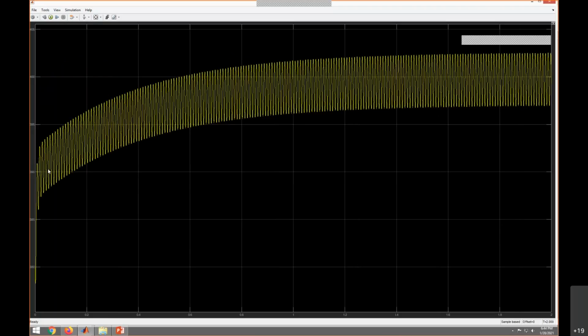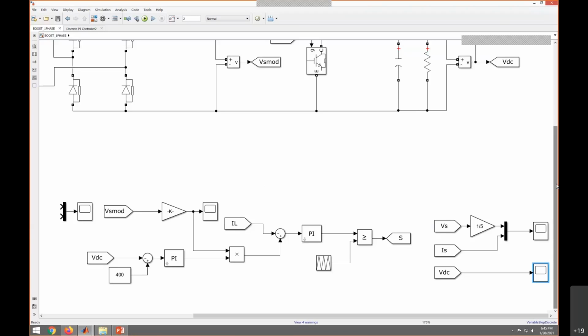See here, this is the output voltage. It is supposed to maintain 400 volts. So here we have 400, right? Here this is moving, and the lowest part is somewhere around 300, or some oscillations are there. It is maintained between 395 and 402. Some 10 ampere ripple is there, and most of the content of this ripple is the third order harmonic only.